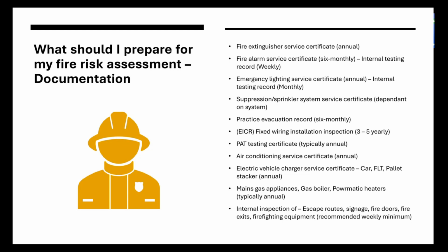Okay, so electric vehicle charger service certificates. So these are not just for cars. This can be for a forklift truck charger, a pallet stacker, any other kind of equipment like that requires a charger. You've got low-level order pickers, which are like ride-on pallet trucks, things like that. Whilst all of your equipment requires the service, your chargers need one too. So just be aware, EV chargers should be serviced annually for electric vehicles.